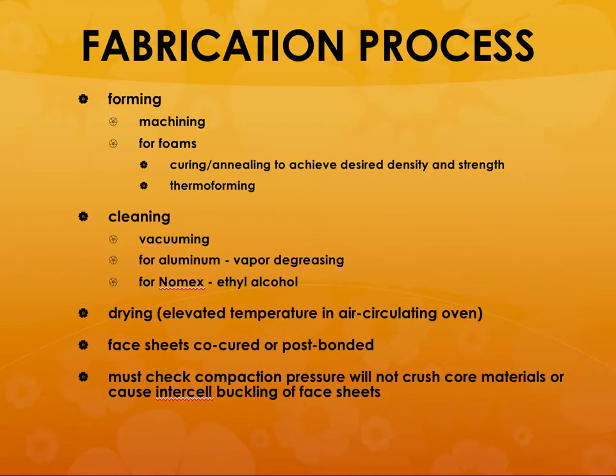And Nomex is a paper core, and you can use ethyl alcohol, which can evaporate, and you apply that to get the right kind of cleaning. And if you don't have it cleaned properly, then it is not going to bond to the composite material. Then you have to dry it, and you can have the face sheets that are co-cured or post-bonded.